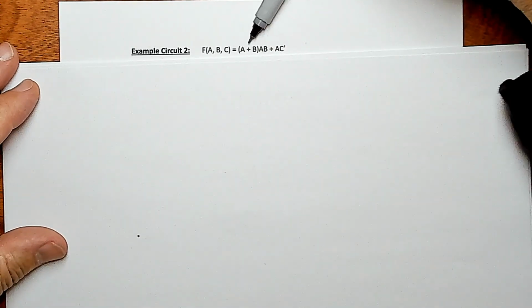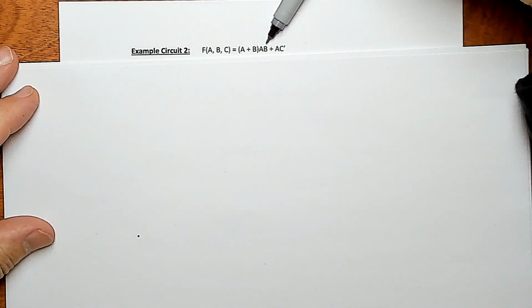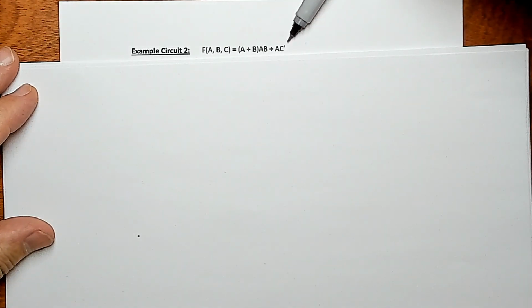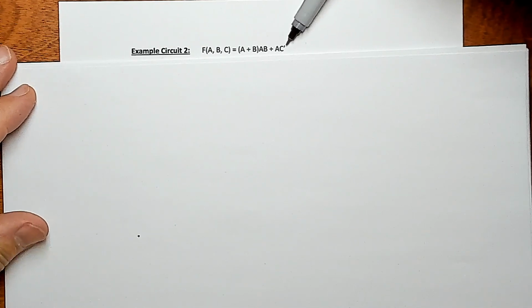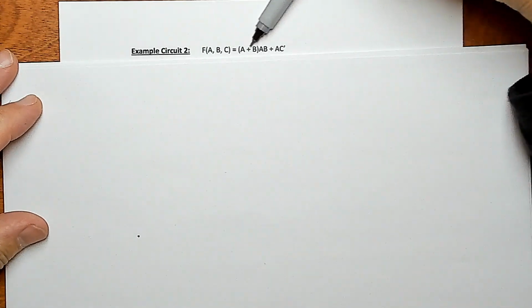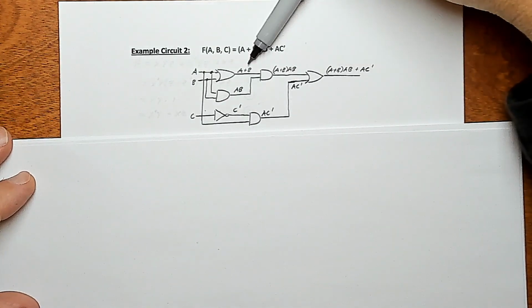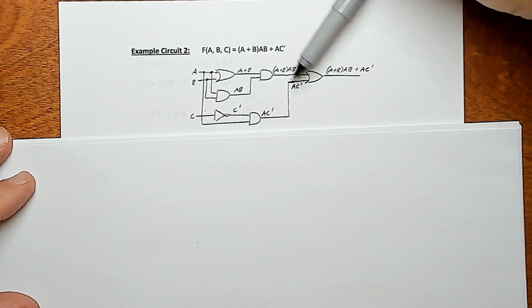We've got an OR gate in here. We're ORing A and B. Then we're ANDing A and B, and then we're taking those two results and ANDing them together. And then we go over here and we take the C and NOT it first. Then we'll AND that with A. Then we'll take that combined result and OR it with the stuff on the left over here. So if you drew a gate diagram, it would kind of look like this. So this is the kind of thing that you're supposed to be able to go back and forth with.